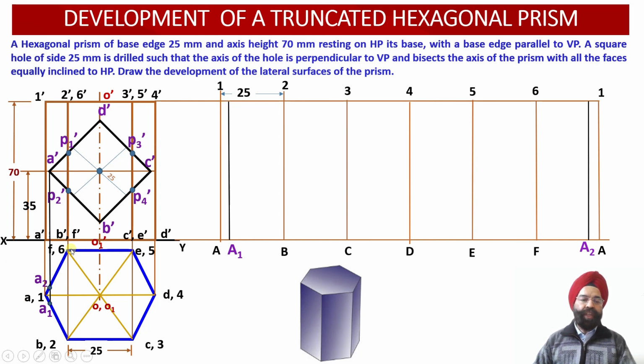Similarly, corresponding to the rear face of this particular hexagonal prism over here, as we move from point F towards point A, at this distance from point F or at this distance from point A, the point A2 will be located on the rear surface of the solid over here. So now we can check at a larger distance from point F or at a shorter distance from point A. So a black vertical projector corresponding to the point A2 has been located over here.